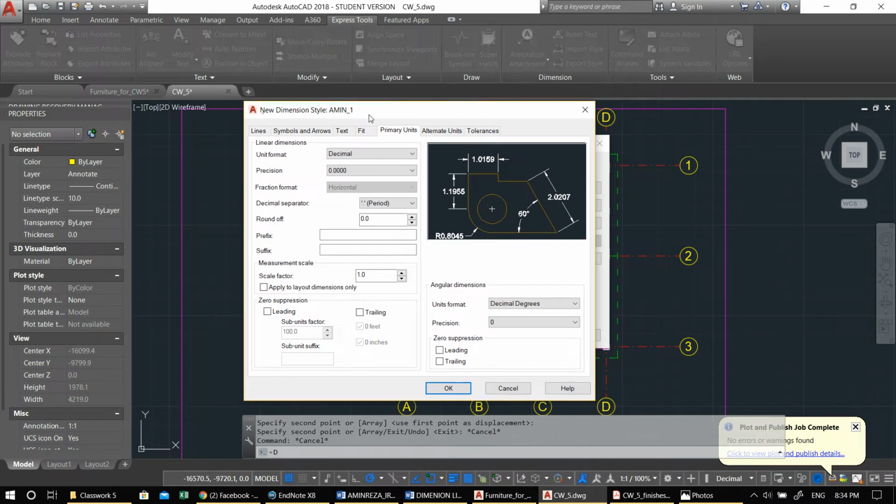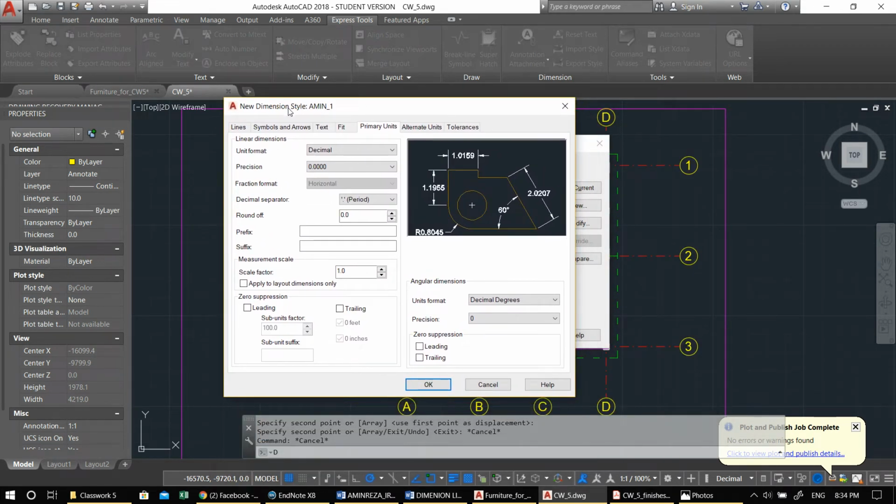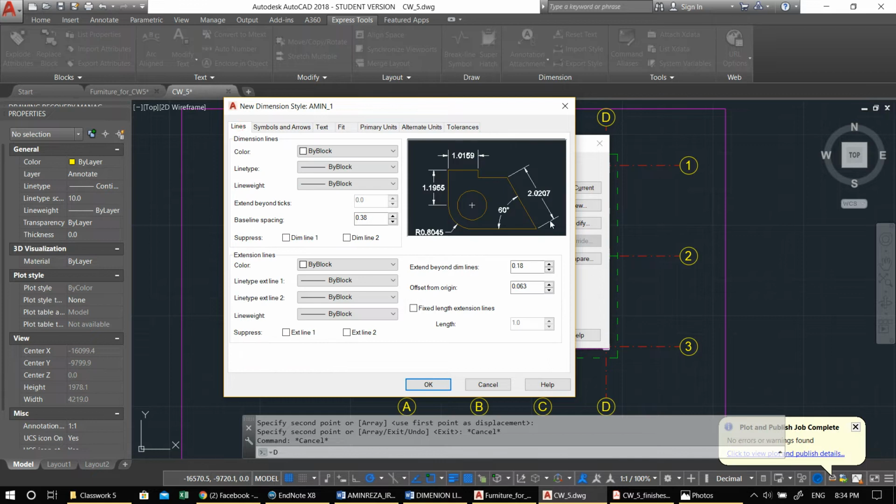So I open it up. After you click OK, this will open up. I'll go one by one through what you need to change. Any number that you see here, these are set by default for people who are drawing in, I think, meters or something like that. I'm not sure. So I found a good rule of thumb, which is any number between 10 and 20 will work here when you're drawing in centimeters. Or let's say bigger, like give it a magnitude of 100. All right. So let's see, 12.